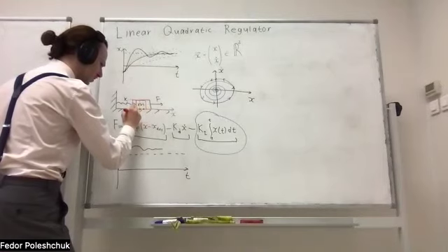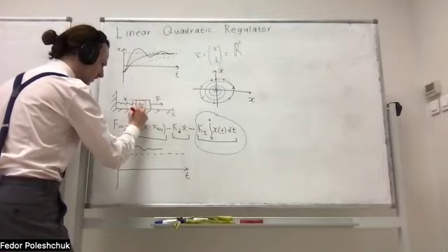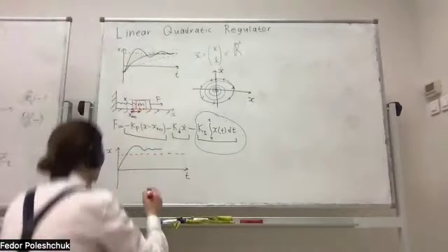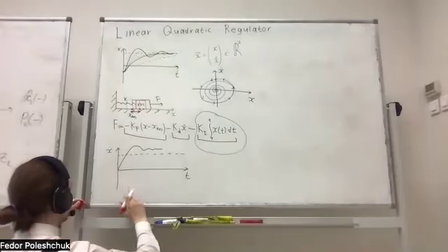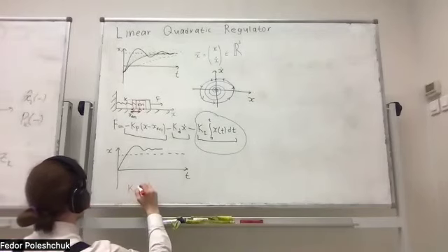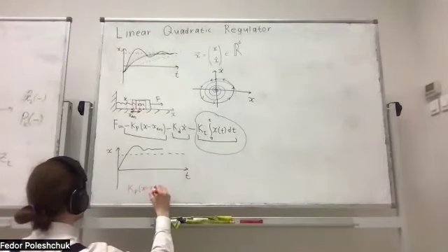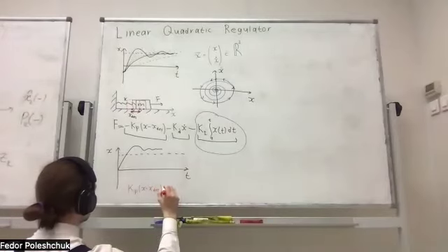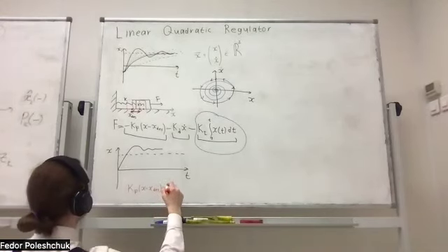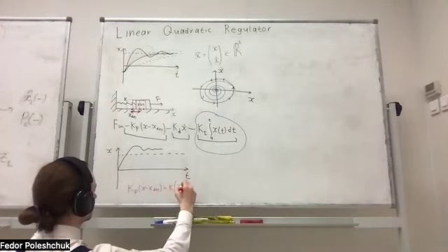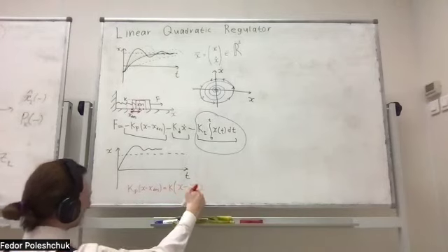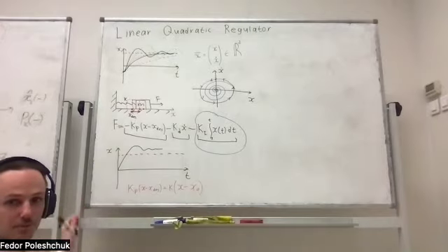The deviation is kind of small, and we can be stuck statically in the position where kp times x minus x desired is exactly equal to the spring constant k times the position of the block minus x0, and x0 is the coordinate where the spring is relaxed. And in that instance, the force would be zero.